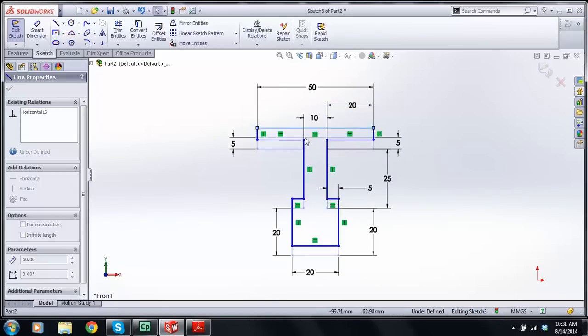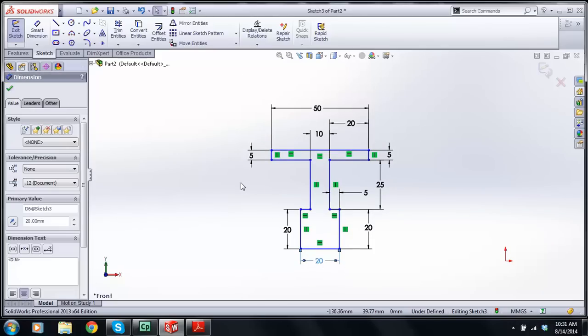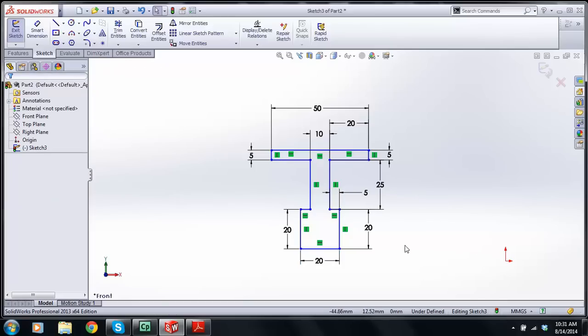Now these lines are blue. The reason they're blue is that Solidworks is telling you that these lines are underdefined. So we need to tie this into the origin. There's your origin, the 0, 0 point. I need to lock it in somehow. I need to lock it into the X, Y, Z space. There's an awful lot of different ways of doing this. I'd rather just tell you the best way of doing it, and then you can learn. I don't want to teach you bad habits.